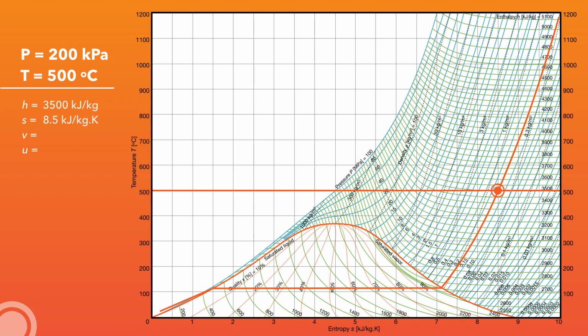The specific volume requires an extra step because the sequence of density lines is geometric rather than an arithmetic sequence with a common difference. First, we understand that specific volume is the inverse of density. Next, we must identify the 2 lines that bound our state and calculate the ratio, 3 1/3 in this case.